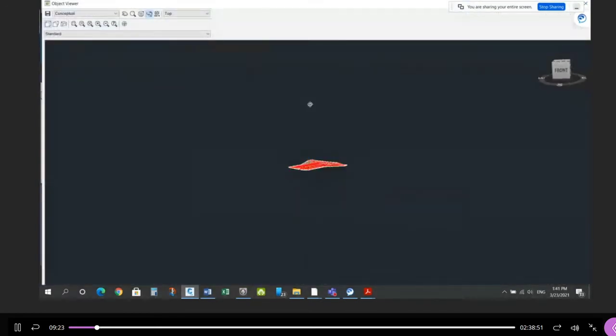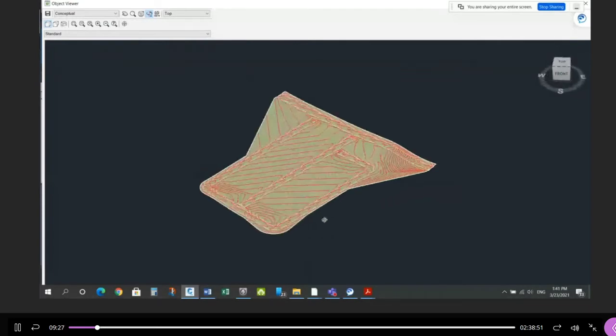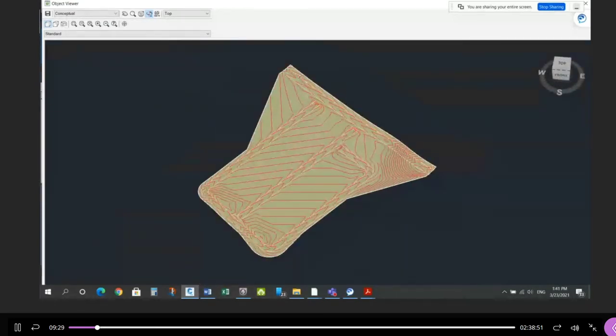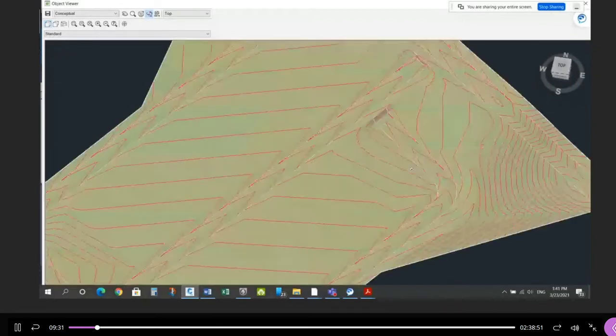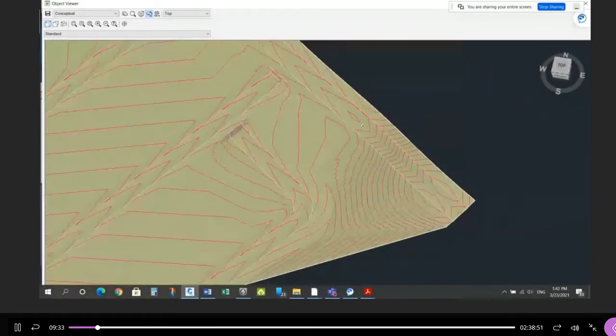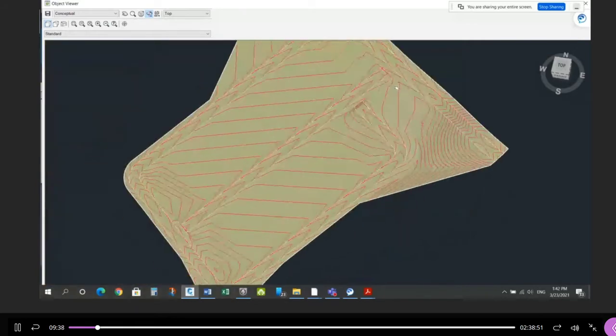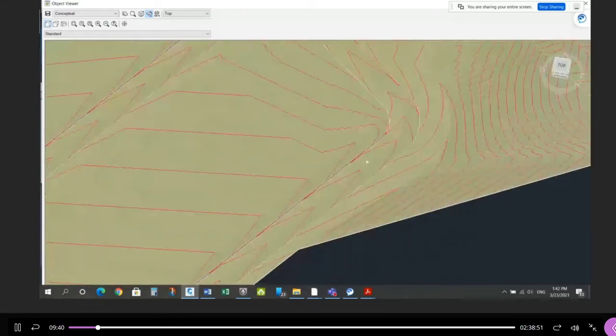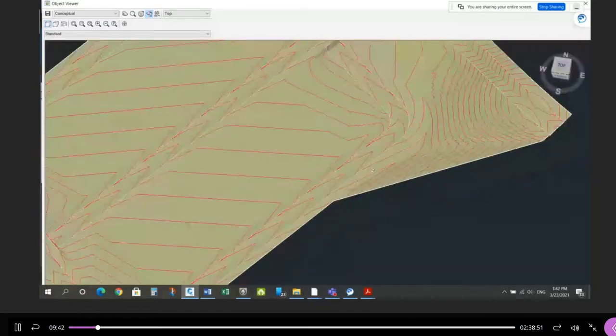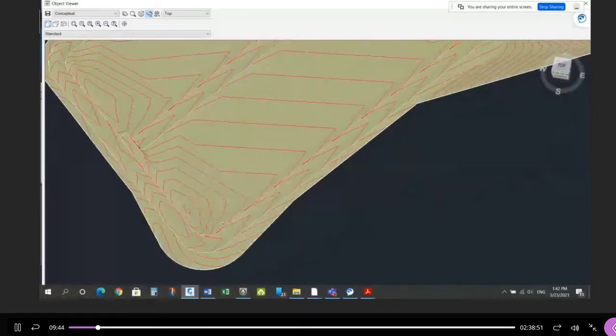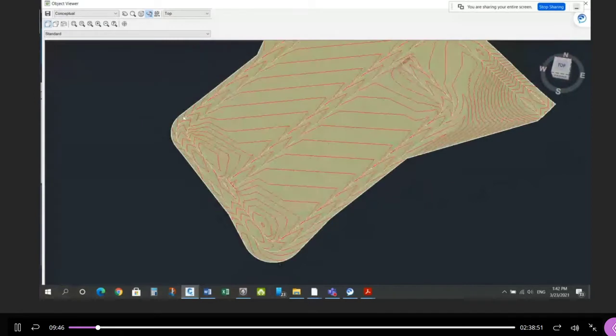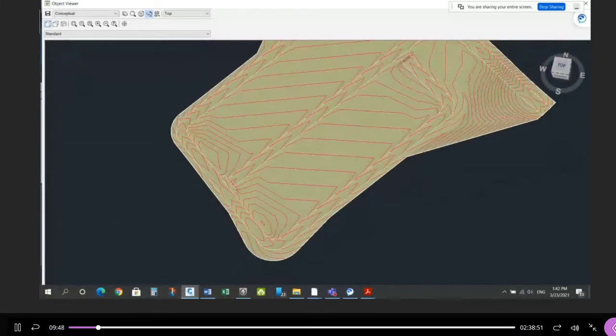At a glance, it should have no spikes, so there's a mark, no spikes. And then the other thing you should see: you may or may not have included Ledger Way. You would have seen this pattern on Ledger Way, a low point near the intersection, a high point across the front of these lots or the back of these lots. And then you would have seen a nice smooth transition through the elbows and a nice smooth transition through the elbow here.